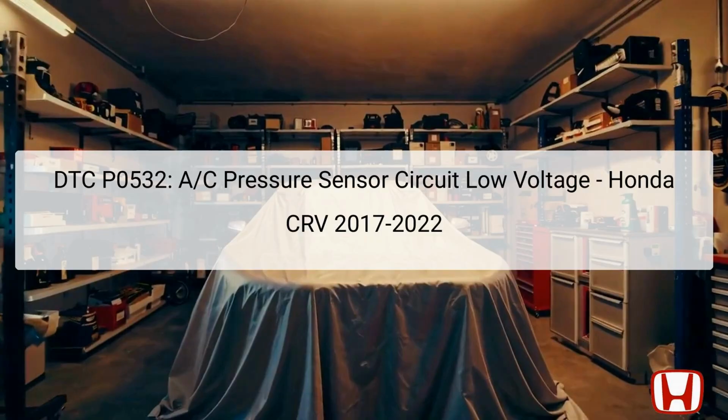This presentation will cover DTC P0532, which stands for AC Pressure Sensor Circuit Low Voltage, as noted in Honda CRV 2017 to 2022 models. This diagnostic trouble code, DTC, indicates a low voltage signal from the AC pressure sensor. The AC pressure sensor plays a critical role in monitoring the refrigerant pressure within the air conditioning system. It provides vital data to the Powertrain Control Module, PCM, which manages the overall operation of climate control within the vehicle.